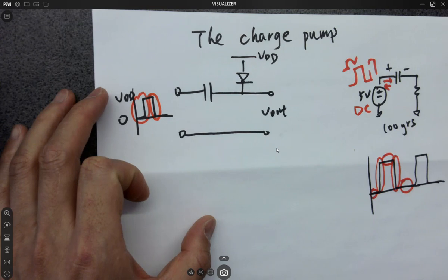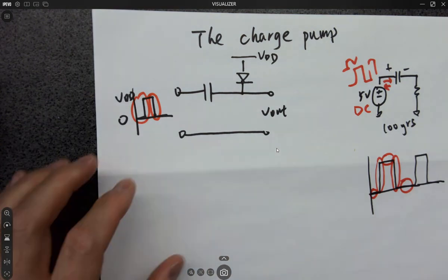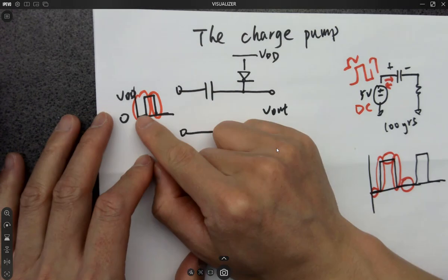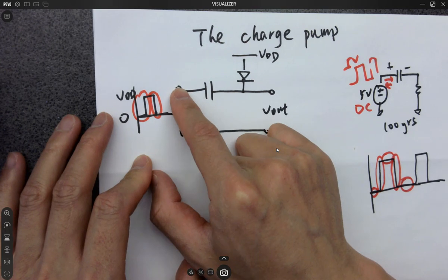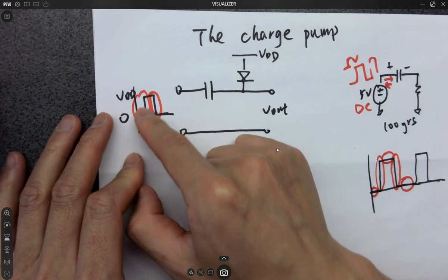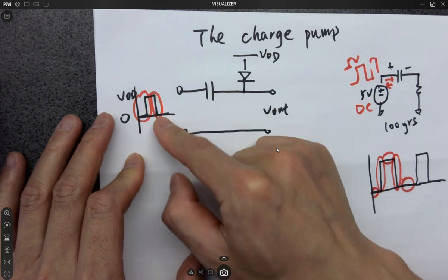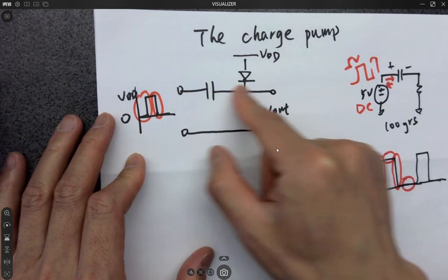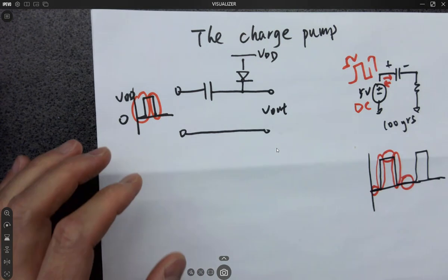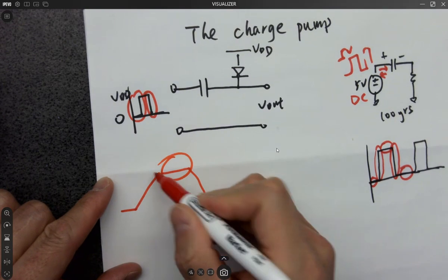Okay? Keep in mind, in the future, if you go to graduate school or if you go to work for a company on some nonlinear circuits with capacitors in there, you need to know that whenever you are charging up one terminal, the same instantaneous signal is passing through the cap to the other side. Okay, and when it's pulling down to ground, it's pulling charges out from the cap. It's doing the same thing to the other side because this ramp here is AC signal. The ramp. Okay, this is not AC, but this is the AC.